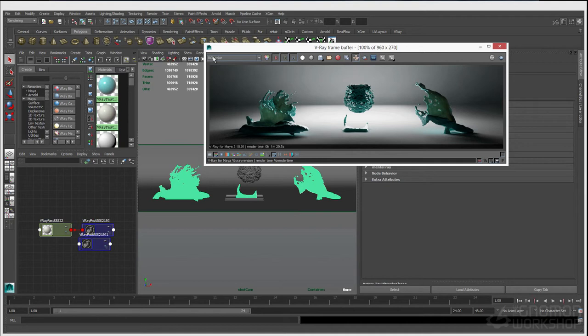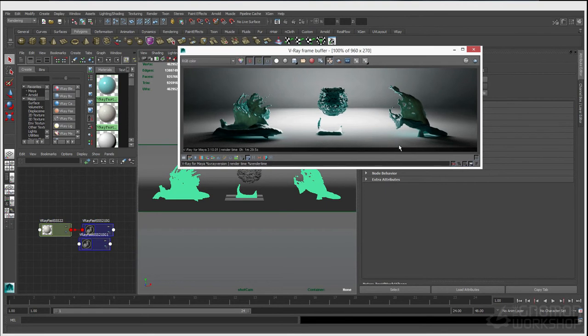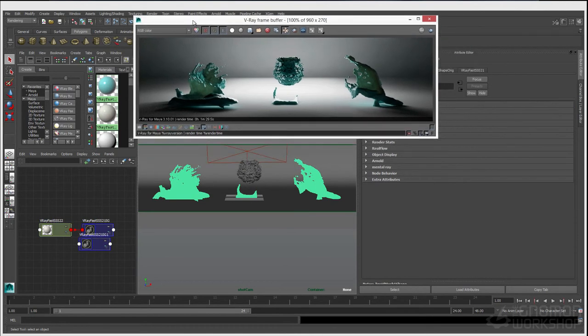Another one of the main ideas of the V-Ray proxy is that they only will ever be called one time. So when you hit the render button and these 3 meshes pop in, you can have basically unlimited copies of that VRmesh file in your Maya file. Well, not unlimited, but wherever Maya would kind of cap out. But you can basically create unlimited counts of geometry. And that's in this first demo here, we're going to be showing an example of that. But first, let's talk about how to export our V-Ray proxy.